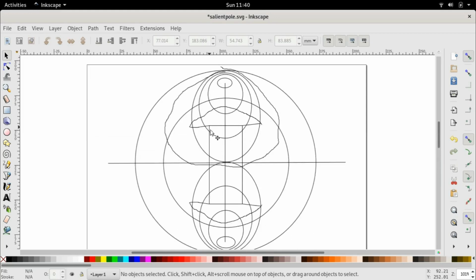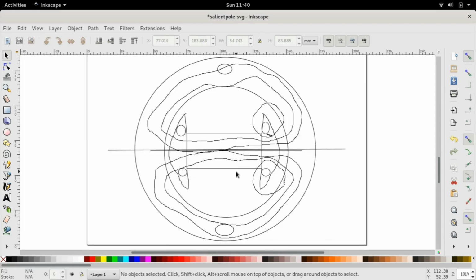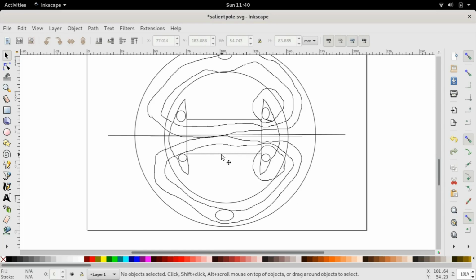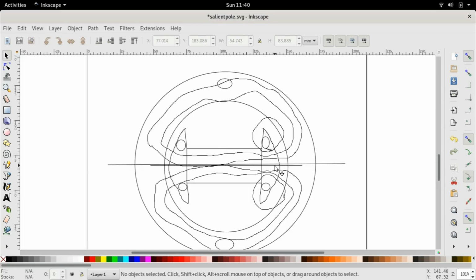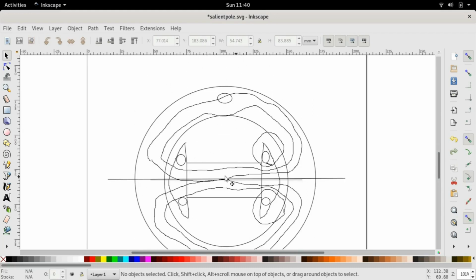Here you see that because the stator is excited and the rotor is moving, the stator inductance is dependent on the rotor angle. Whereas here, because the rotor is excited and the rotor is moving, there is no dependence of the rotor inductance on the rotor angle. The reason I wanted to show you this is that sometimes we tend to jump to conclusions. You can jump to this conclusion, thinking that because it is a salient pole rotor and the self-inductance is a function of the rotor angle, the rotor inductance should also be a function of the rotor angle. But that's not the case.